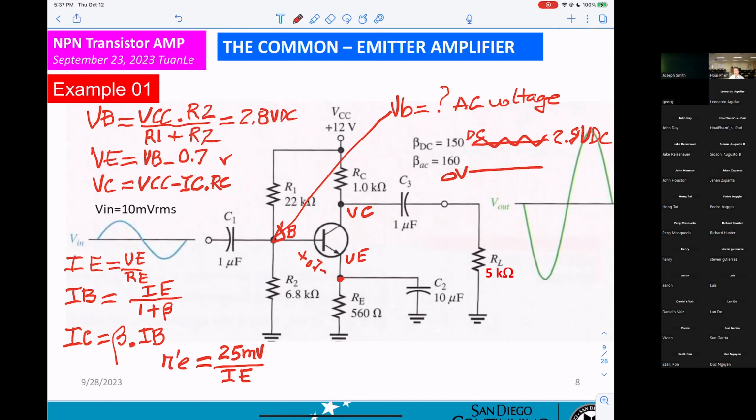And for channel 2, you have to do the same thing. Next, you have to make sure your scope probes are matching. If you use 1X, then both have to be 1X. Or if you use 10X, both have to be 10X. Okay? They have to be matching. That's the minimum thing you have to do before you can do anything else.